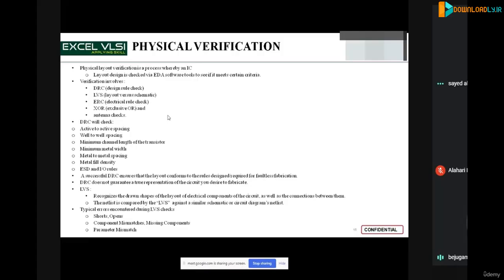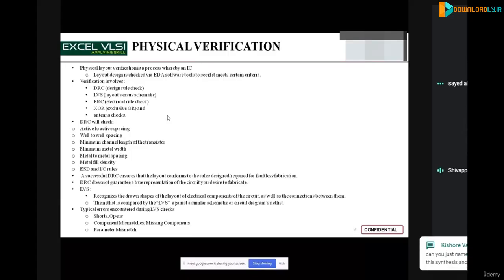If the gate level inputs and outputs are not placed according to the rules, we get such IO rule violations. Just to add on here, physical verification will be done after the physical design process in the ASIC flow. And the rule deck, whatever some of these we have listed, will be coming from the chip manufacturer. They will give DRC, LVS, all these details.